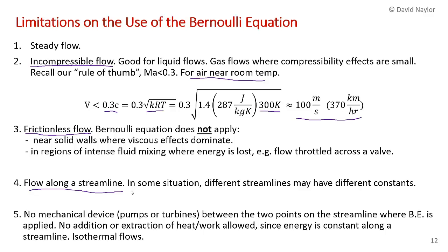You would normally be applying Bernoulli's equation to isothermal flows. No pumps and no turbines. Again, later in this chapter, we'll relax that assumption. I'll show you how to analyze systems that have pumps and turbines and losses due to valves, which is what practical engineering problems usually involve. But for now, when you're using Bernoulli's equation, we can't deal with those issues.